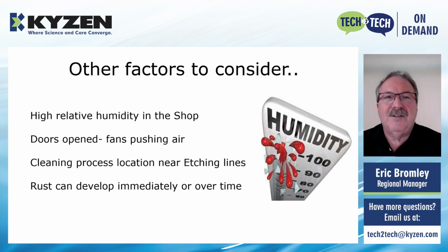Some of the other factors to consider with rusting is the high relative humidity in shops. As many of us are aware, metal fabrication shops are very rarely air conditioned, so you're subjected to the heat and the environment that the building is put in. So there's a lot of open doors and fans pushing air around inside the building for operator comfort and to remove some of the heat. But that can also bring some of the humidity and some moisture, and it'll settle on the parts.